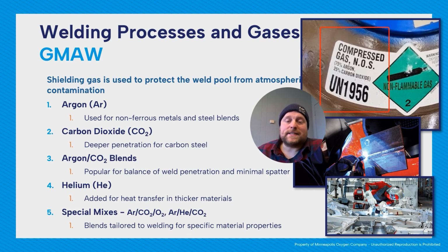You might see out in the world, or you might have done this yourself, where you're like, hey, I'm doing a spray transfer. I really pumped up my wire feed speed, my voltage. Yeah, here I am spraying. If you still are running 75-25, you're not spraying. You're just running an extremely hot short circuit. So it's important to make sure you change those gases if you're changing that transfer method.